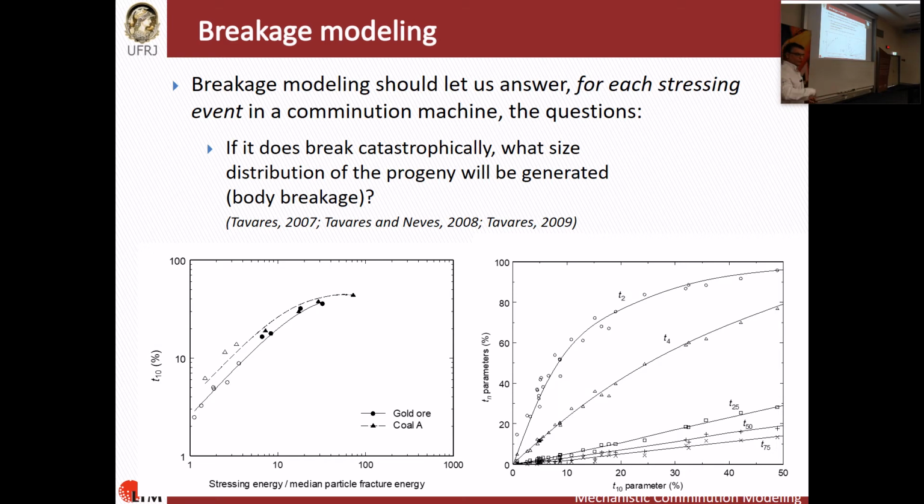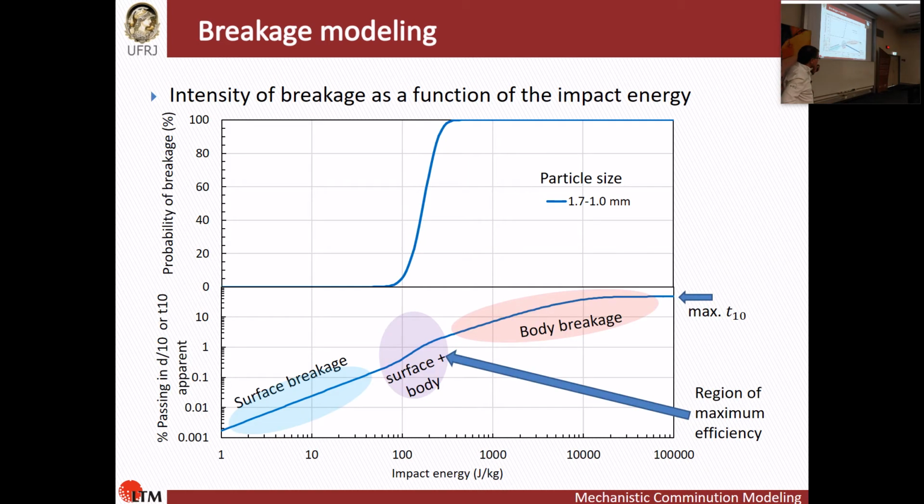We know drop weight testing, impact testing, we do that. We just did some tweaks in this model to be able to cover what is actually breaking, never analyze material that is just suffering surface abrasion, not to mix the two mechanisms. But except for that, it's very simple to do the T10 procedure that was developed and used a long time ago. So just to illustrate what this really entails to put these things together and the importance of this breakage probability,